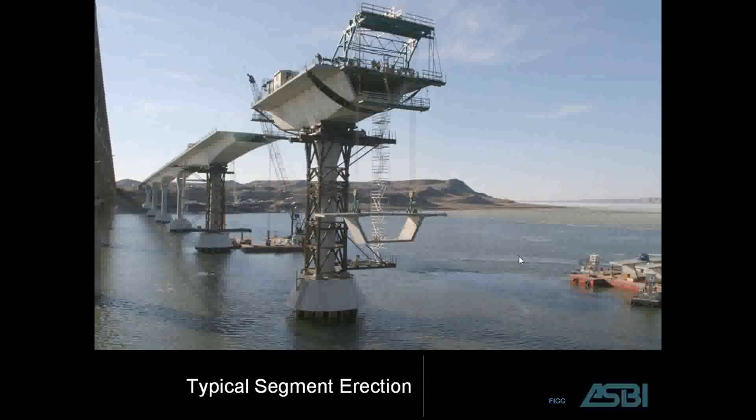Here we see the erection of the segment, and it's being erected using beam and winch. There's multiple ways to do this type of construction. Beam and winch is one of the methods. So the segment is transported underneath the cantilever location. The segment's attached to the cables, and then the beam and winch lifts the segment up into position.